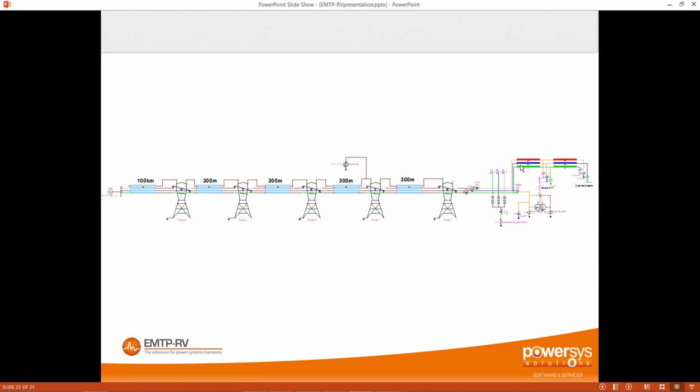So it's a very detailed way of building the network. So obviously here we are talking about very high frequency. The span of the line, or the length of the line here inside the substation are very short, and so to be able to model and to simulate such a case, we'll have to use a very small time step, something like 15 nanoseconds, to be able to simulate that very precisely.